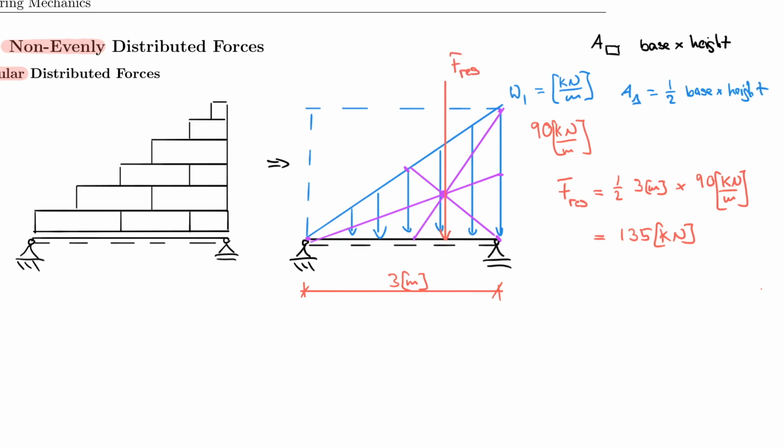But what you need to remember is really the distance from the support reactions, right? Because you need that lever arm. So what you need to remember is this distance. And you can probably already tell from this picture, and you might have already discussed this in high school, that this distance here must be 1/3 of the length, and this here must be 2/3.